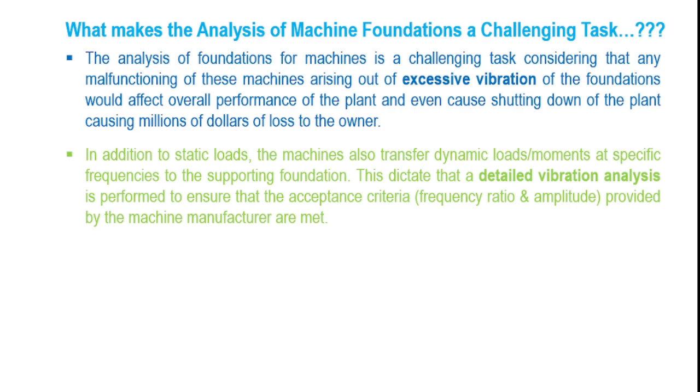That is, in the case of conventional foundations, we need to perform just a static check to ensure that the pressure which the foundation transfers to the ground is less than the soil bearing strength, and that the resulting settlements, whether total or differential, are within the limits. But in this case, in addition to the static checks, you need to perform a detailed vibration analysis. And I will tell you that for a machine foundation designer, this will be consuming almost 90% of his time. So a detailed vibration analysis.